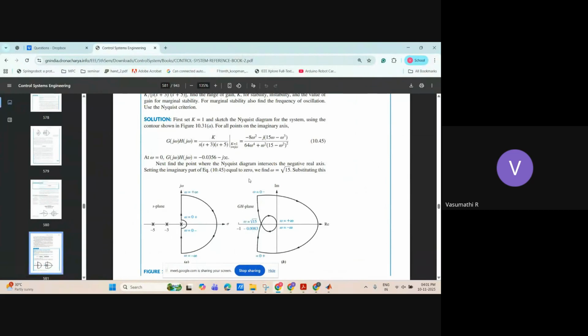Okay. Actually, it is not rotating. It is going around it, but it is not rotating. So consider this as a 0. Rotating the poles in the anti-clockwise direction will be 0. But I have an open loop pole at minus 0.3 or plus 0.3 in the RHP. So if we check the closed loop pole, it will be positive. So according to our formula, Z is equal to N plus P, where P is 1, N is 0. So Z will be 1. But here why is it 2?